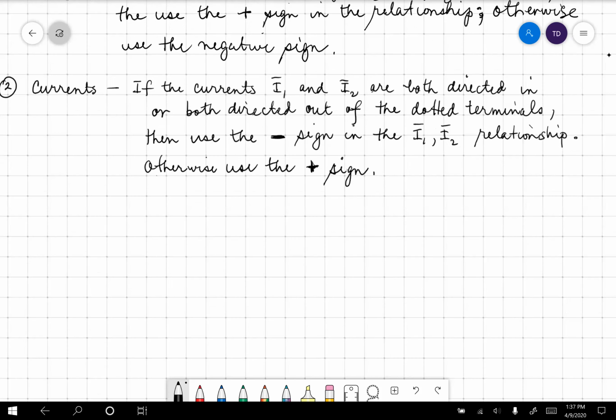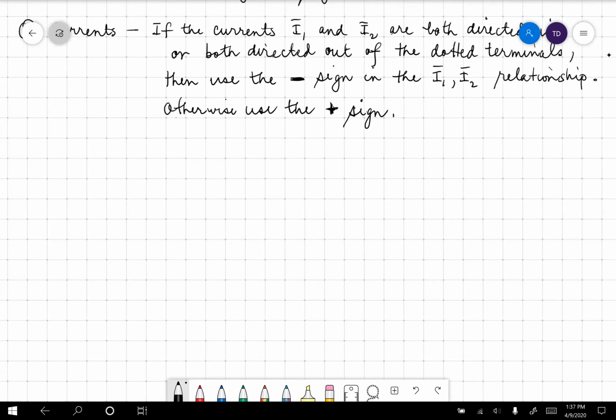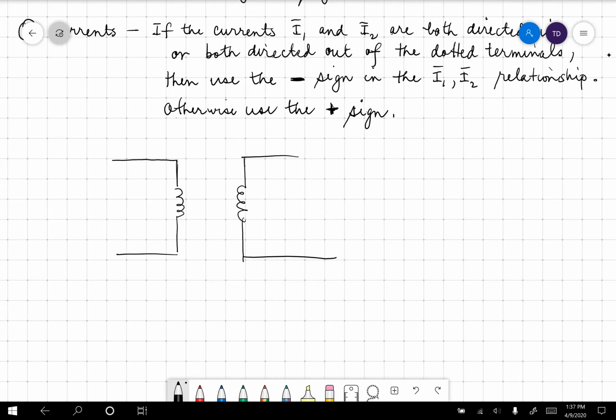And so what you'll see is you'll see a lot of transformers that look like the following. Dots are on the top almost all the time. Ideal transformer. Here's your ratio, whatever it is, 1 to A. That's why a lot of people use the 1 to A notation, because if the first number is 1, the second number is always A. And then they show this, plus minus V1, plus minus V2, I1, and I2.